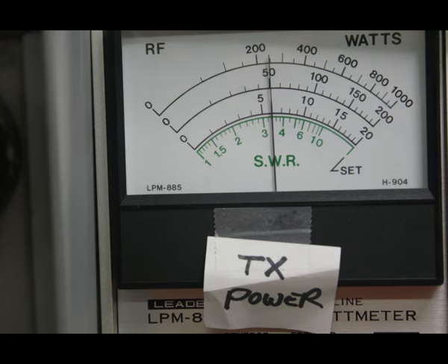So now I've gone back to the transmitter end of this whole setup, and I've retuned that input tuner. I don't care what you guys call it. You can fight with each other all you want on that. As long as we know what it is, I'm good with it. So I've readjusted the matching network, or the antenna tuner, or whatever you want to call it, at the input end, so that my ICOM 746 Pro now sees a 1-to-1 standing wave ratio.